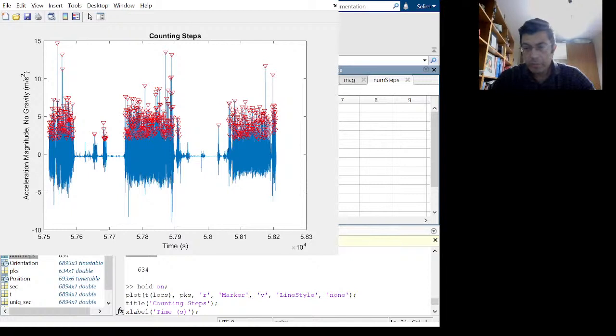Jem says we must log new data every time in this method. Sure, Jem. If you are asking about the live data usage, as I understand, that was possible in some previous versions of MATLAB. I tried to do that as well, to use the sensor data from the phone instantaneously, but I couldn't make it. If you look it up on the internet, you can see similar results. So you have to create a new log, get the data, save it, upload it to MathWorks Cloud, and use it in your MATLAB desktop or MATLAB Online.